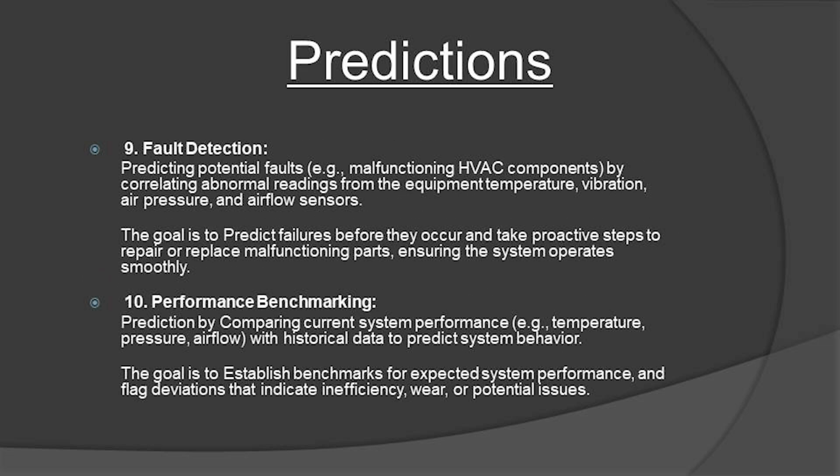Fault detection: predicting potential faults, like malfunctioning HVAC components, by correlating abnormal readings from the equipment temperature, vibration, air pressure, and airflow sensors. The goal is to predict failures before they occur and take proactive steps to repair or replace malfunctioning parts, ensuring the system operates smoothly.